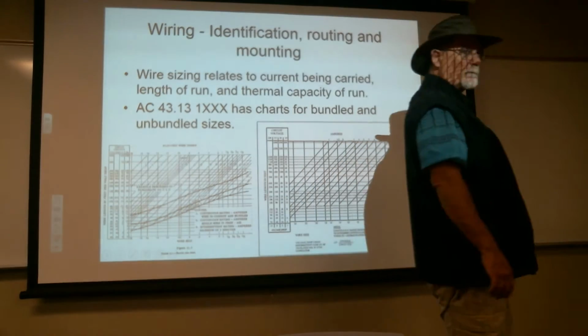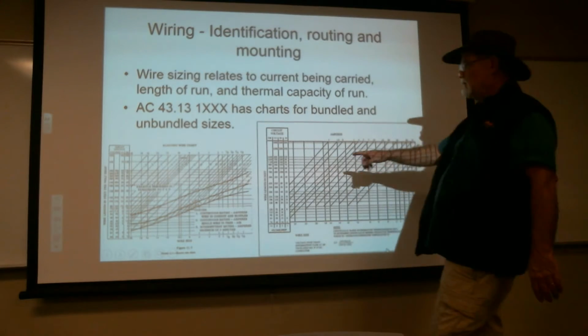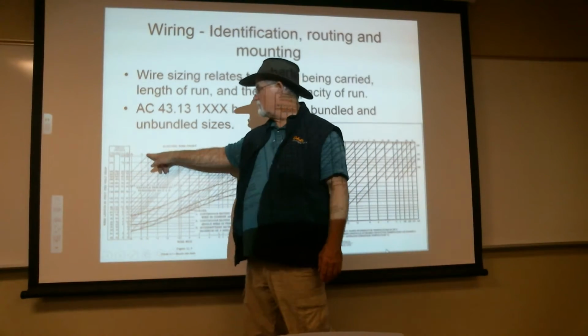So the smaller the number, the thicker the wire? Right. American wire gauge works that way: a bigger number is smaller wire. And unfortunately, when you get to 1, you're kind of out of luck. You can't go any smaller. So what they did is they said there's 0, then double 0, triple 0, and quadruple 0. Where's the number for what kind of wire it is? Those numbers here, that's the gauge of the wires right here.